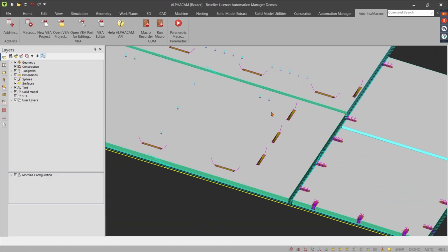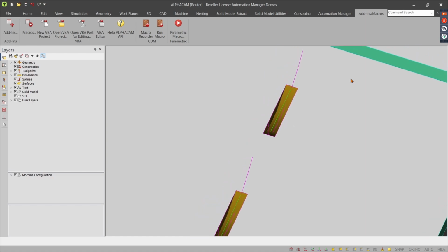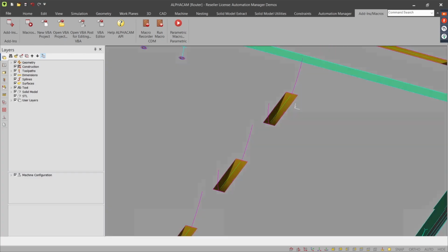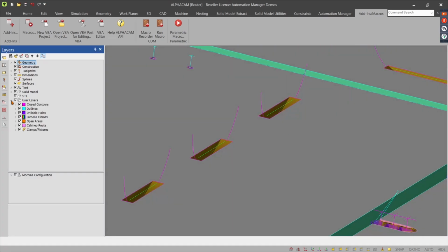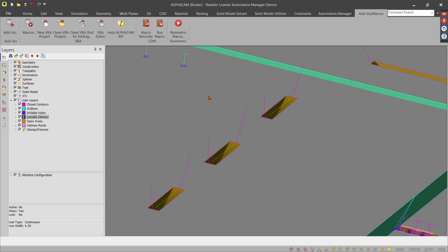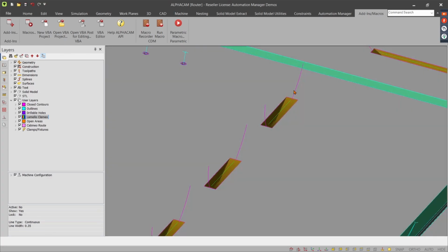The macro I've run has scanned the job for grooves, or slots, of a certain width on a certain layer. It's then projected a center line across that layer, which I've then applied, and it gives you the layer. You see I've got the Lamello Clamex layer there. That is that green line in the middle. I've run that in the background of Automation Manager using the production pack Automation Manager event extender. What it's done is allowed me to project that line, assign the Clamex macro to that with my machining style I've created from it, and machine the Clamex. It's a really uniform system to achieve.